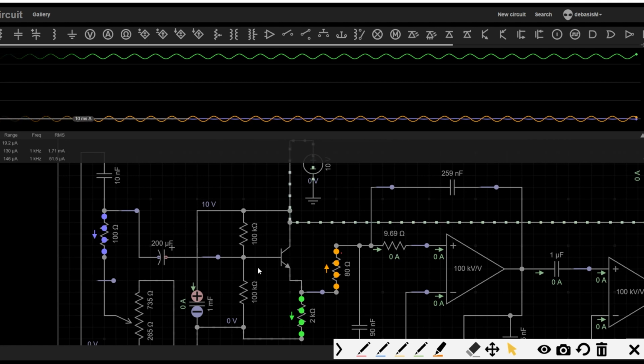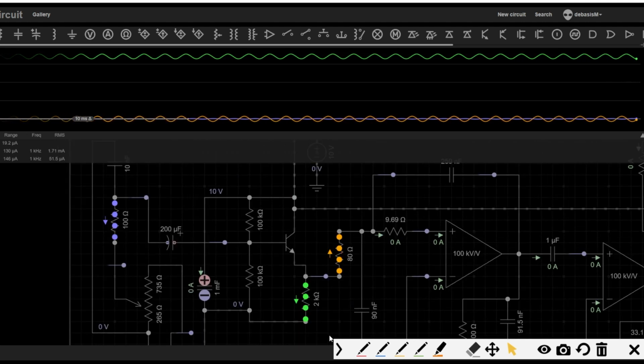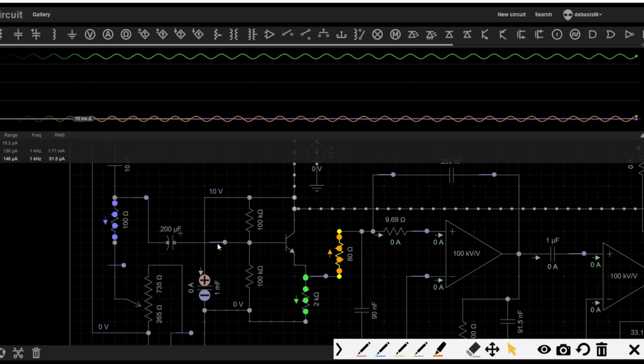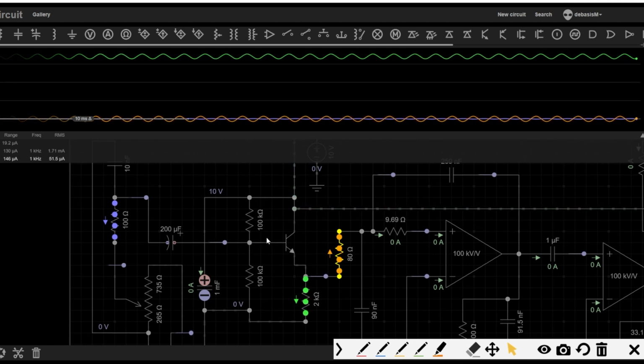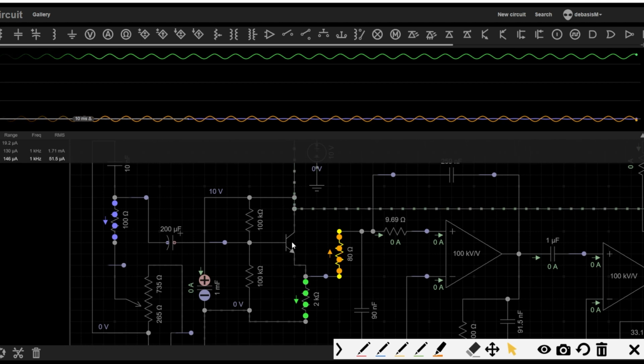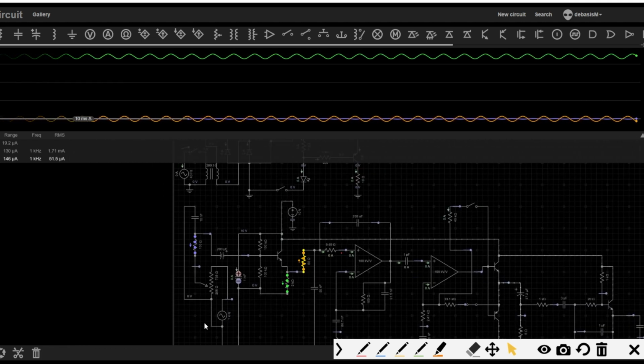Plus you don't do any kind of audio processing, etc. If you amplify the signal before that, there will be lots of noise. So the main reason is the efficiency of this transistor. Why is the efficiency so low? The reason is that in this audio signal cycle, you have to keep the base sufficiently high so that in both the negative cycle and the positive cycle it's giving current flow. You see here, effectively in the entire cycle this is on, and I can show you if there is no audio signal.